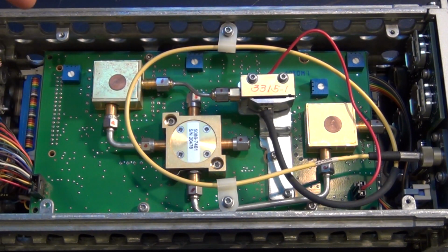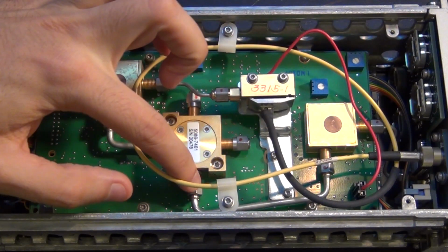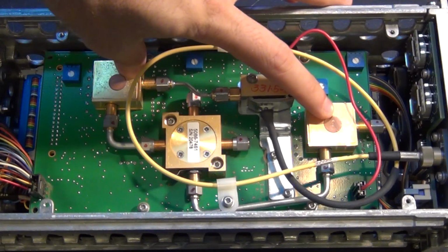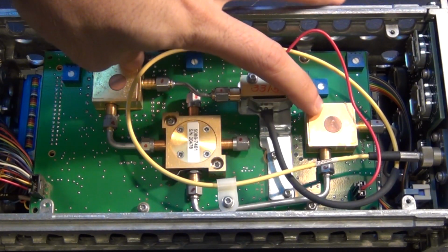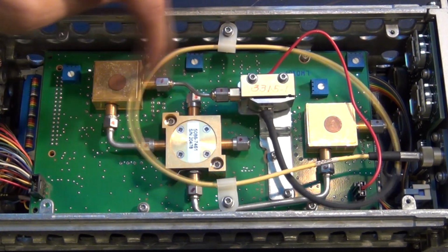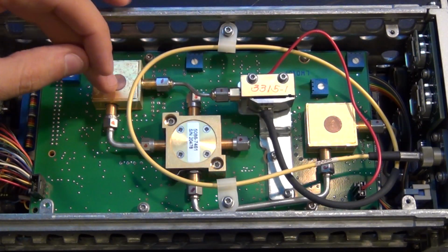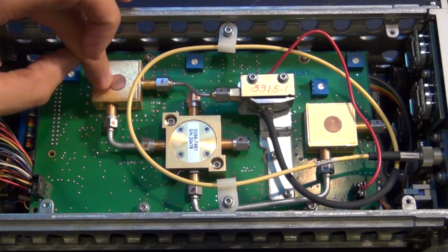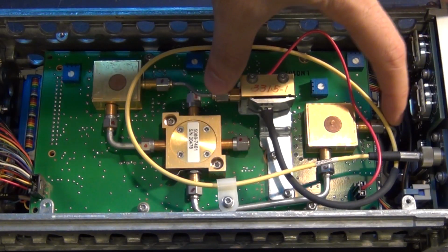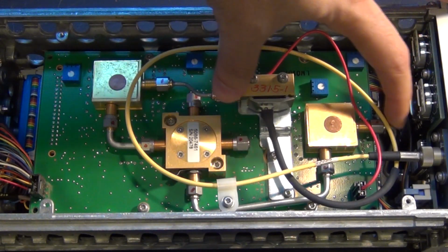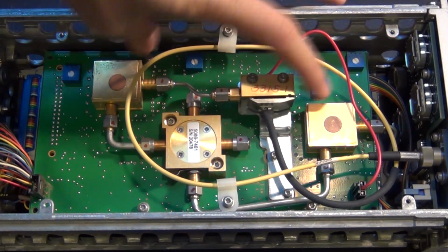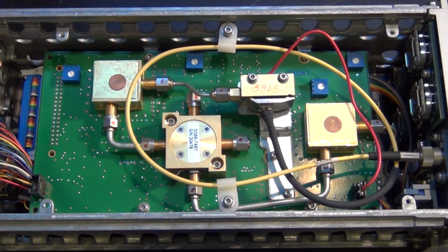For the purpose of right now, it suffices to say that this will generate very narrow pulses from our trigger signal. And you will have to generate two of them, because one goes to this sampler and the other one goes to the other sampler. And they are willing to replicate the samplers as opposed to combining them, because they really want to have the ultimate signal integrity between these two. So now you have two IFs which can then be selected between very easily. It's much easier to select whether you're looking at the IF of this versus the IF of that, rather than try to select between these two signals where the noise and the linearity is critical and the bandwidth is critical. That's why they would rather replicate the sampler and put up with the cost of that than to put a switch between these two analog inputs.